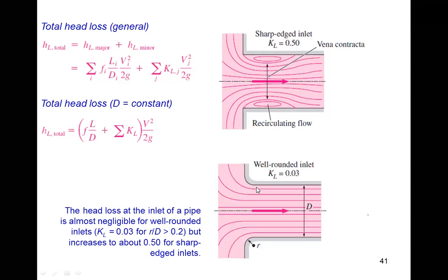I mean to say that whenever you change the direction of the flow, or you put in a sudden contraction or sudden change, you will always have a loss. That is what I want to say here. A sharp change gives very high losses, and a rounded, curved or slow change gives low losses. Is that fine here?